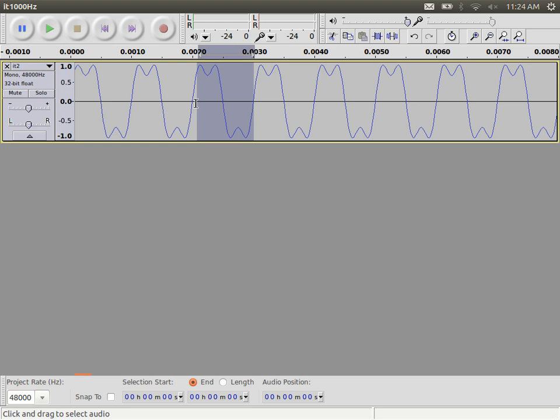In the highlighted area, the signal is high for some period of time, and then it's low for some period of time. We could say that that represents 2 bits, a bit 1 and a bit 0. If we transmit the high signal, it's as if we're transmitting a bit 1, and if we transmit the low signal for some time, a bit 0. So 2 bits there in the highlighted area.